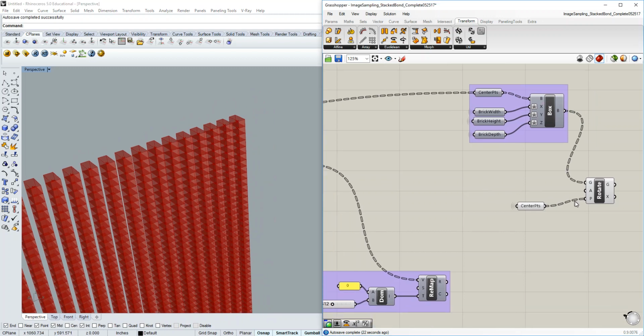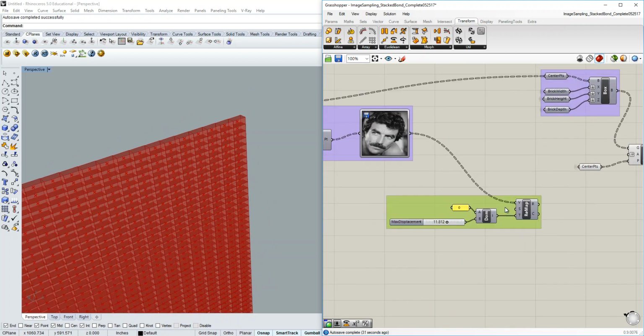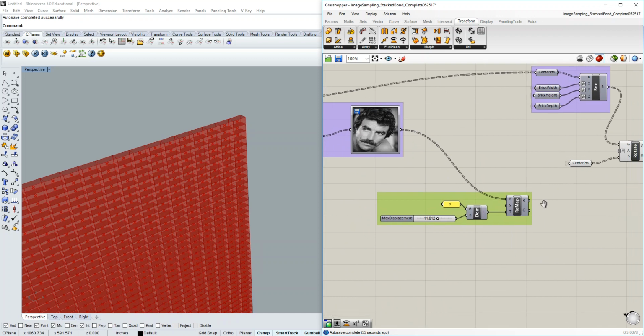Now, we don't really deal with radians much, but you'll see the angle is asking for radians. Let's go ahead and right-click and set that to degrees. So now it's asking for a rotation angle in degrees. This whole remap is going to control our rotation angle.